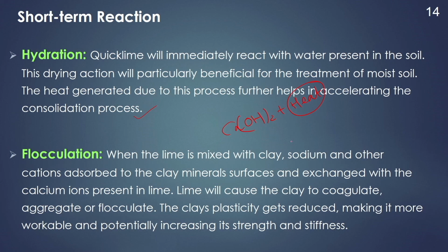Therefore, in the hydration process, the water present in the soil will react with the quick lime and that will form the calcium hydroxide along with the heat, and this heat will remove some of the water.